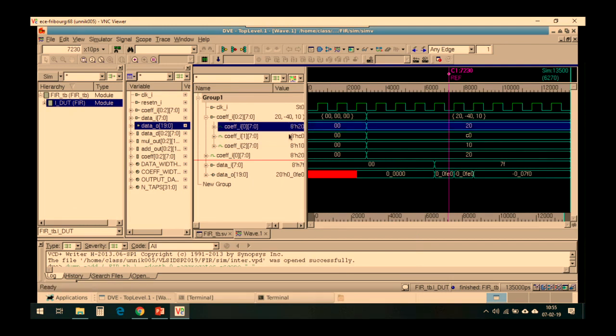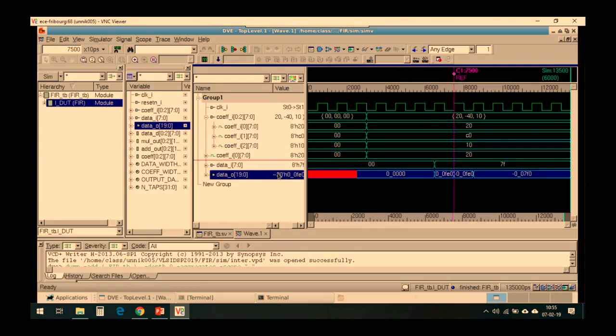So this is the number representation we have used, and an important thing to note is that these sorts of scales are entirely defined by the designers. The tool does not understand that this is to be interpreted as 0.5 or 0.25, but these are defined by the designer based on their requirements, and the designer can choose where to place the fixed point to decide the scale of these values. So that's a bit about what this is.